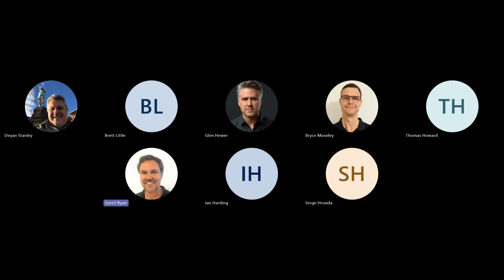And then the other one that I have here is how do we manage the DALI emergency light testing? What a lot of people do is they use third-party software. You have NetX automation, you have iceberg, you have other visualizations like that. And we've done that in many projects where we'll set out a whole building and we'll schedule the DALI emergency light testing from there. So you'll have a visualization that'll map your whole building for you. You'll be able to test the DALI lights, the emergency lights in groups. So I might say, I'll test the first floor today. Tomorrow I'll test the second floor. And it'll go off and automatically do it in the background.